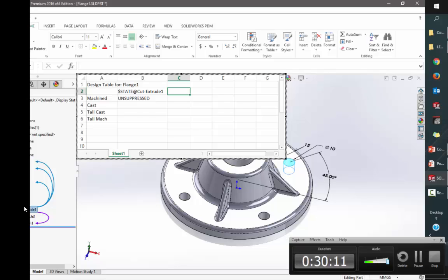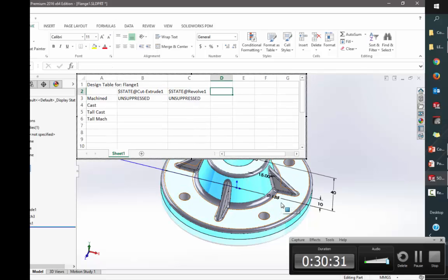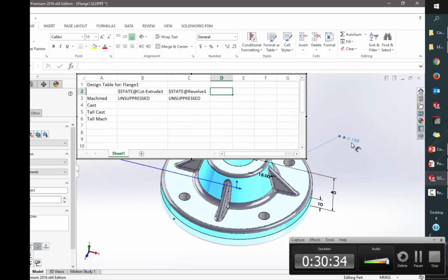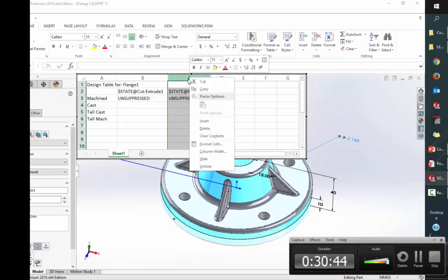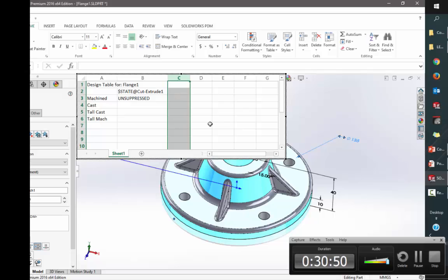The other thing I wanted to control here was a dimension. Now, the dimension I need is in the base. And in SolidWorks, if I want to see a dimension of a feature, I simply double click on the feature and the dimensions are presented to me. Do you see the little downside I'm going to run into here? I'm going to have to come over here, double click on the flange, and then I can see the dimension I need to adjust, but notice what happened when I double clicked on the flange. It said, oh, you want to control this as well too. No, not really. That's not what I wanted to do at all. So I'm going to go ahead and right click on the cell or the column and then delete it. Now it's not controlling it. That's how easy it is to change it.